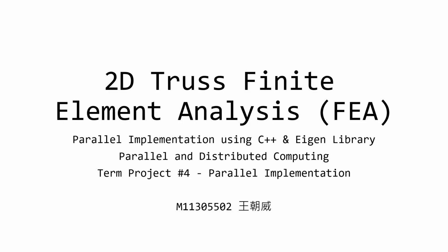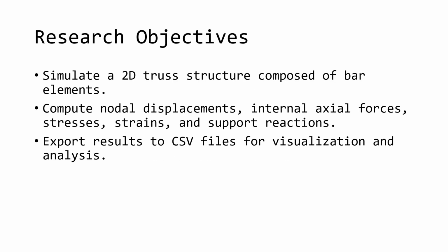Hello everyone, today I will be introducing my project, a 2D truss finite element analysis using a parallel implementation in C++ and Eigen. The goal of this study is to simulate 2D truss structures composed of bar elements, calculate nodal displacements, internal forces, stresses, strains, and support reactions, and export the analysis result to CSV for further visualization.